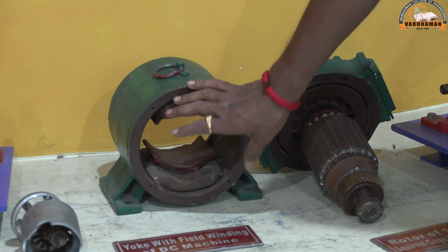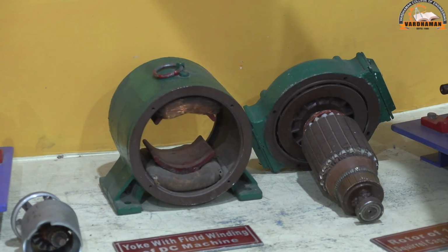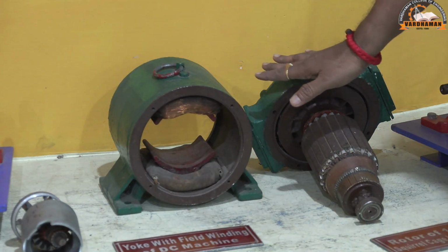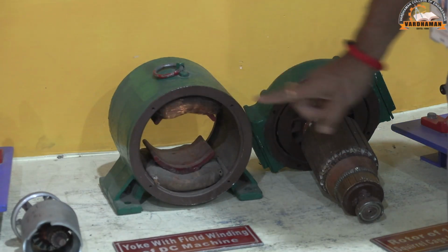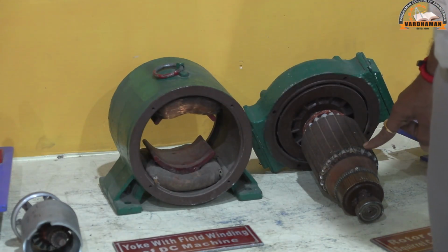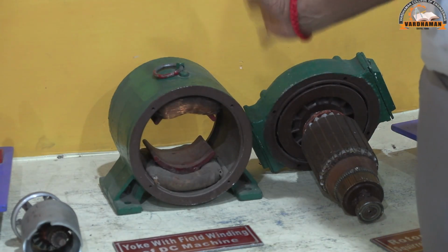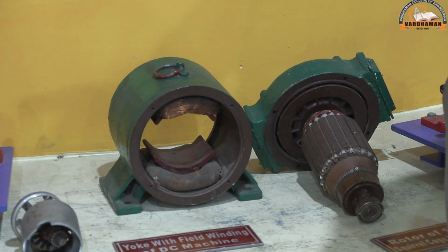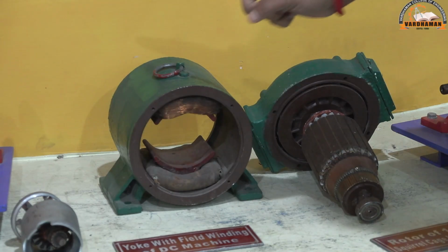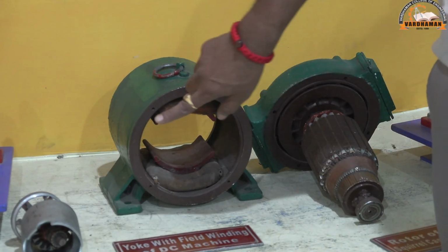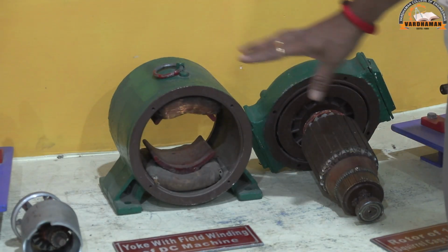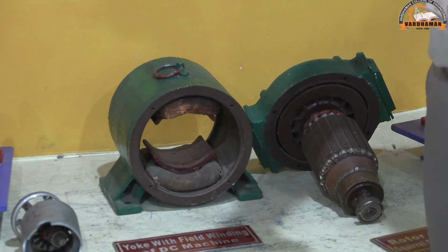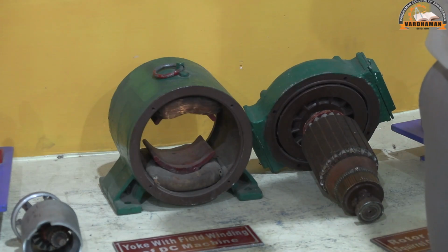It depends on the input power supply. We discussed AC motors and DC motors. Depending on the excitation methods, DC motors are divided into two types: separately excited and self-excited. Depending on the connection in self-excitation: in separate excitation, there is no other variant because we have no connection between field and armature. In shunt, we have a connection between the field coil and armature. If it is parallelly connected, that means F1 to A1, F2 to A2, parallelly connected, it is called a shunt motor.